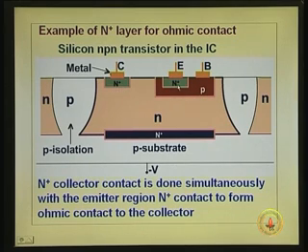the emitter. Now, you can see, if you want to make a PNP transistor, you will have problem, because you will have to do n plus contact to the n base region. That has got to be a separate step. Here, this step is automatic with that step, but in the PNP transistor, it will be P plus, this is P region, that P plus can be done.